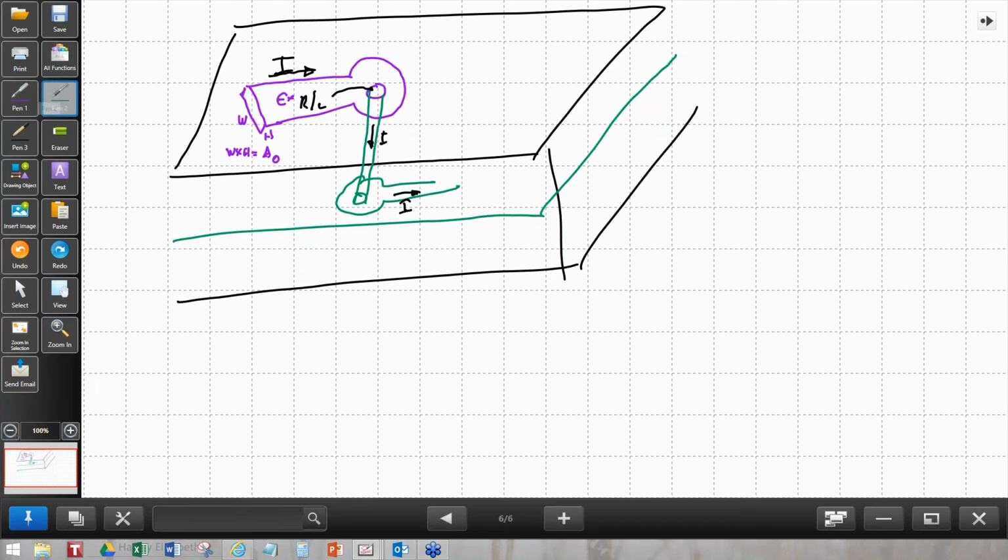If you look at the other trace, you'll see that it also has a thickness and a width, and therefore width times height is the area on the inner layer. Ideally, if there were no special heat problems, you'd say, great, if I have the same amount of cross-sectional copper on the top as on the inside, then it would have the same drop per unit length. That's great. But the outside can dissipate heat way better than the inside. So if you are thermally limited, you can get by with less copper on the outside, but when you get to the inside, you need more copper.